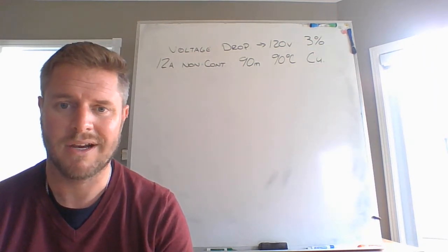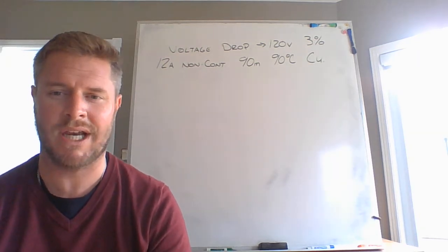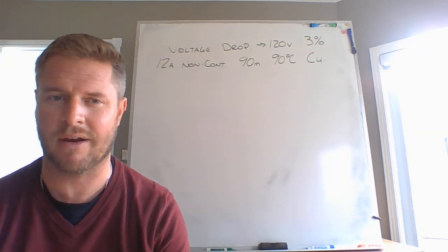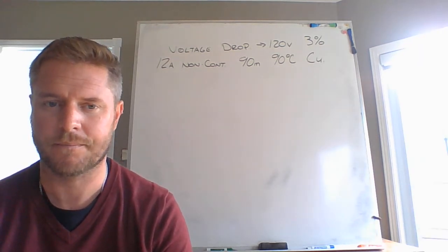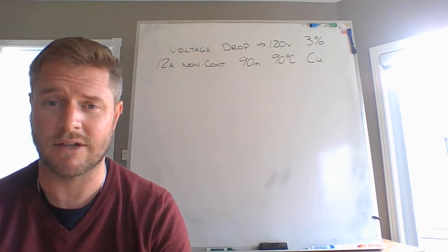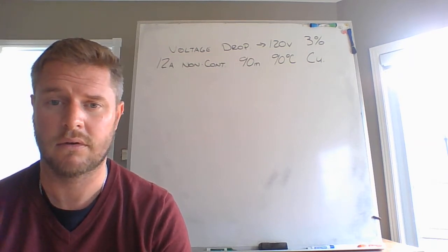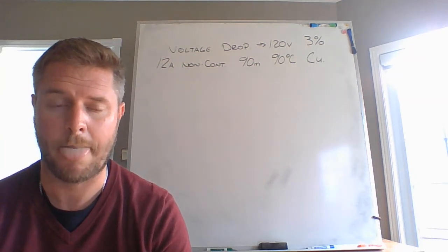No, not really. Because I know that I'm not going to be able to go 90 meters on a 12 amp load with 14 gauge conductors constructed of copper with 90 degrees Celsius insulation. I know I'm not going to be able to go that far, especially 90 meters. That's a football field. That's a long way away. 12 amps load, 120 volts, long way to go.